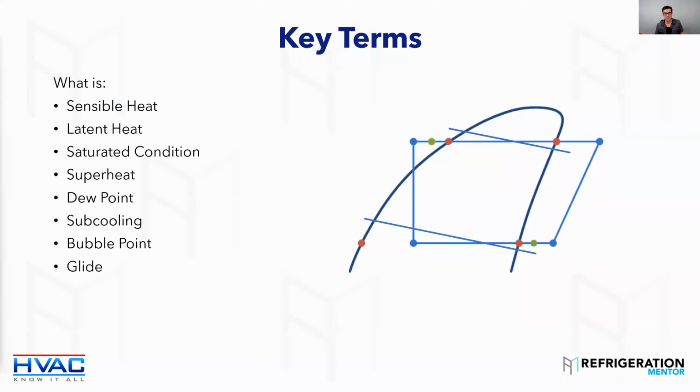People tell me pressures, I'm like, what's the temperature? Because we're really dealing with temperatures. More so important, if you get in the habit of troubleshooting by temperature, especially with all these new refrigerants coming out, when you're talking to another technician, it's going to make it a lot easier. Exactly. 110 Fahrenheit condensing, not, oh, I got 275 PSI. That means nothing to me. What refrigerant now? But if you tell me a temperature, then I can comprehend it.